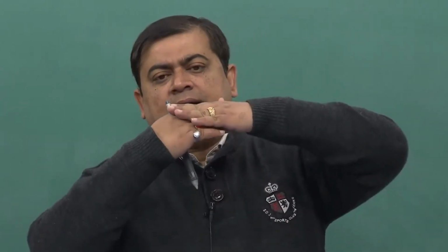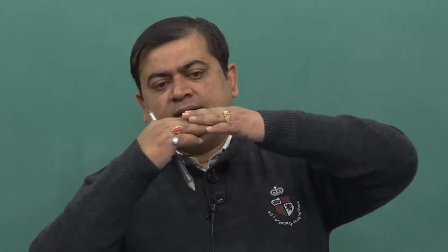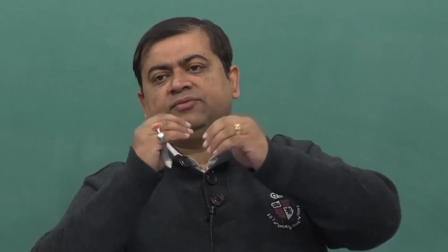So, typically the practice that is followed is that for a spherical pattern, for example, or for a very large casting, let us say a casting of a wheel, you should have a half and half pattern. So, therefore, there is an upper half of the mold and a lower half of the mold. Lower half is normally known as drag and the upper half is the cope, and then these two are actually having a parting line, but the pattern is kept in a manner so that you have the split pattern. You have half inside the lower portion and half the upper portion.